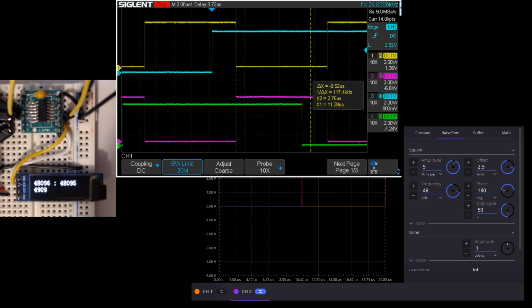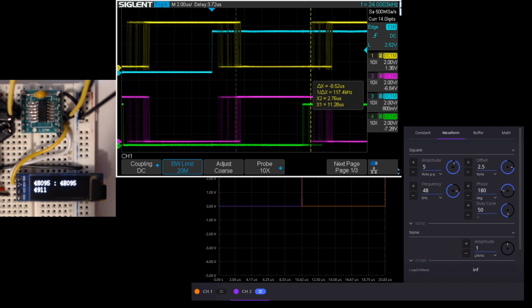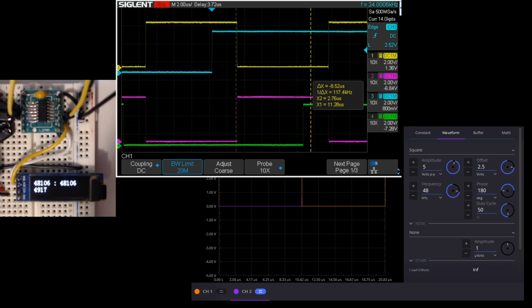So now let's get the scope running again and adjust it to try to see what's going on. So I'll do a single capture and use these cursors again. Let's see, like so. So here we have the rising edge of IRQ1, and here we have the toggle point. So at some point after that toggle point, like in this space here, the context would be restored and the main loop would start to run.